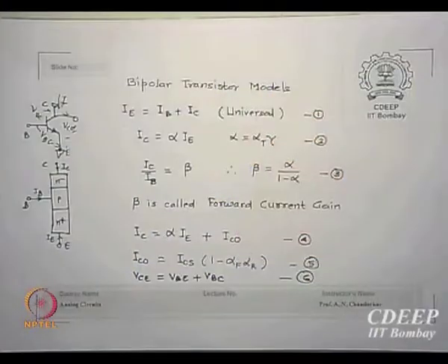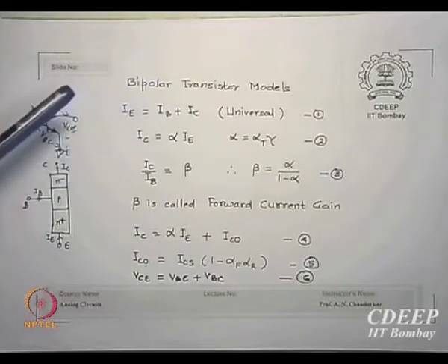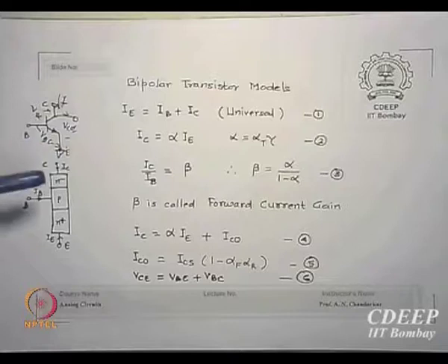Okay. We were discussing bipolar transistors yesterday. We shall continue with that, starting with a typical BJT. The basic equations we wrote last time, and very important for us, is that the emitter current is always the sum of base current and collector current. This stems from the physics that whatever is injected from the emitter side partly recombines in the base and the rest goes to the collector, so base current plus collector current must be equal to the emitter current.